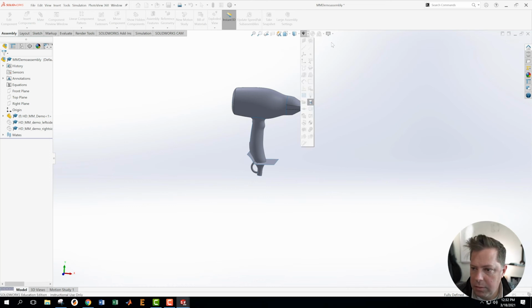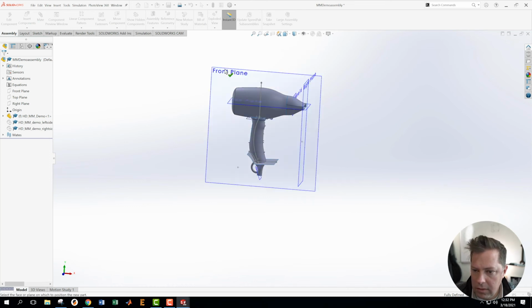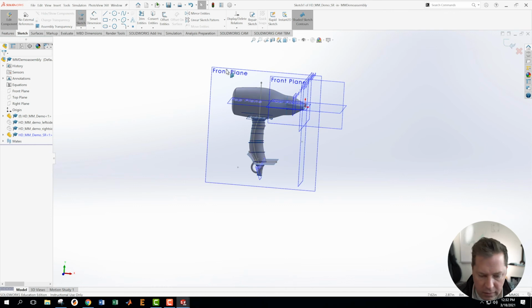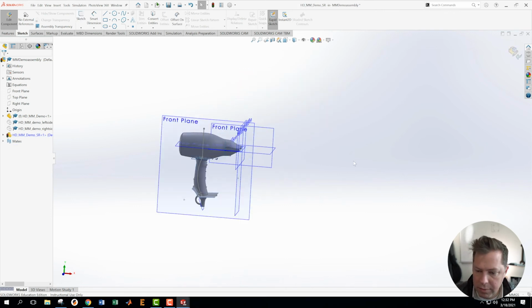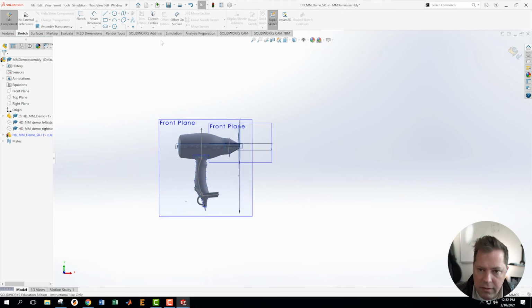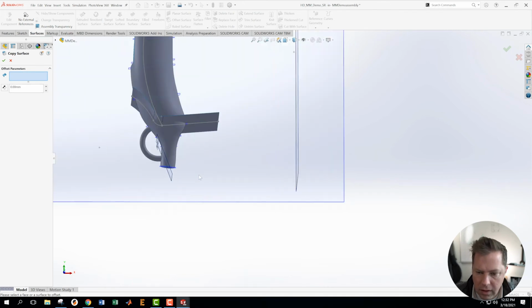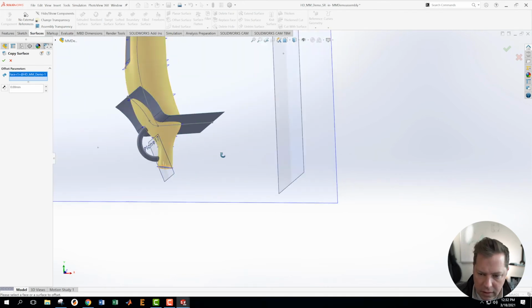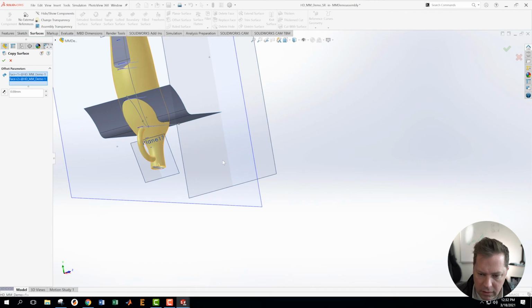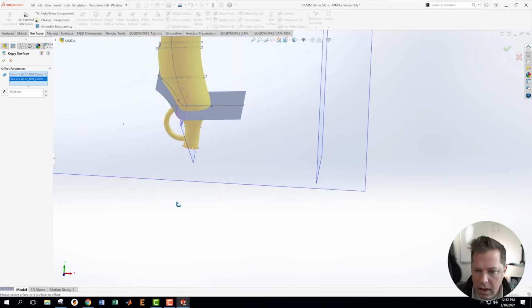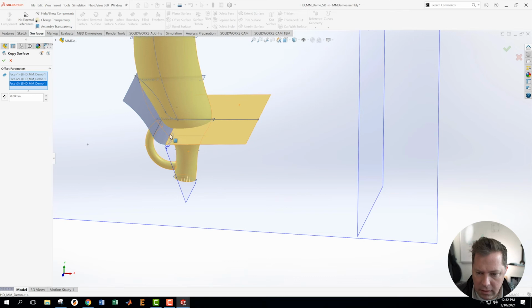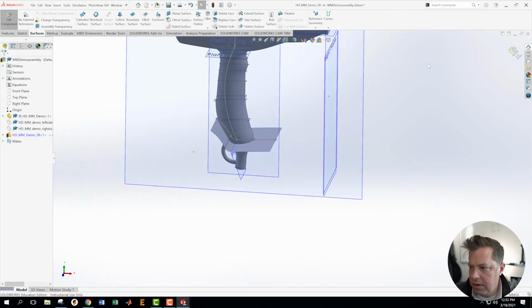What face am I going to put the thing on? I'm going to use the same face we've used for everything else. I'm going to tell it that that's what I want. Now I'm editing this brand new part, which is my strain relief. And I want to go into surfaces, offset surface, set my offset surface to 0. I want to get this surface. And I want to get this surface. And I need my cut planes, so that's this one, and this one. So those are going to be copied in.